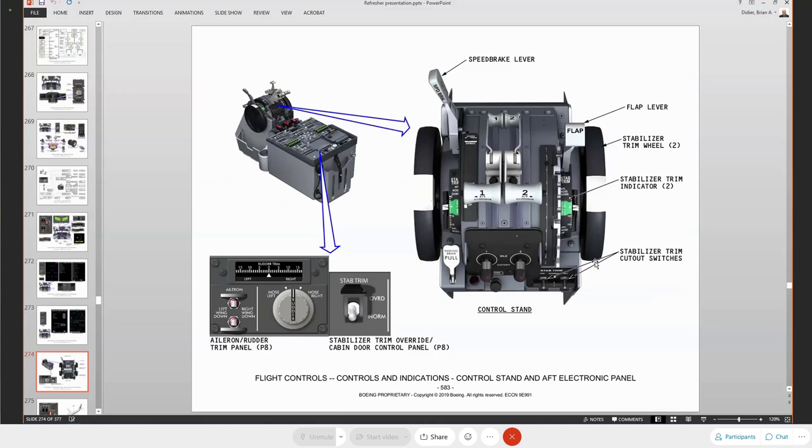So those are indications. The panels, controls, speed brake lever handle. Speed brake lever, it's the same handle, same position that you have on the placard on that side of it. Inside the control wheel, if you remember on your NG, you had an armed switch that was set by your speed brake lever, and you have an RTO micro switch.